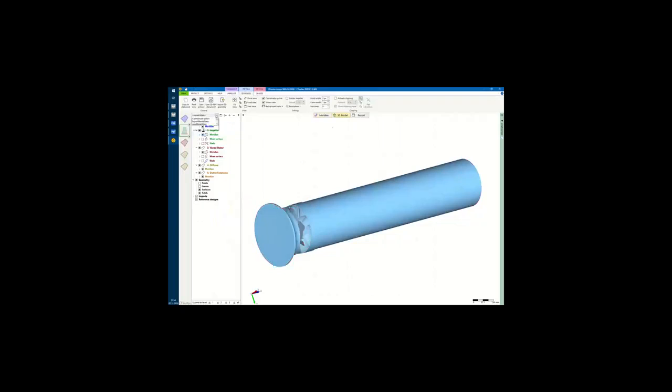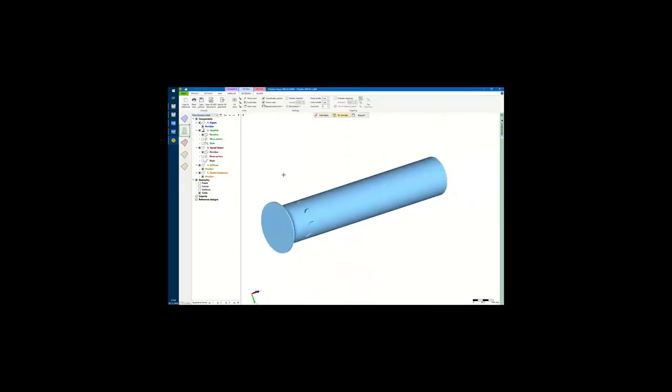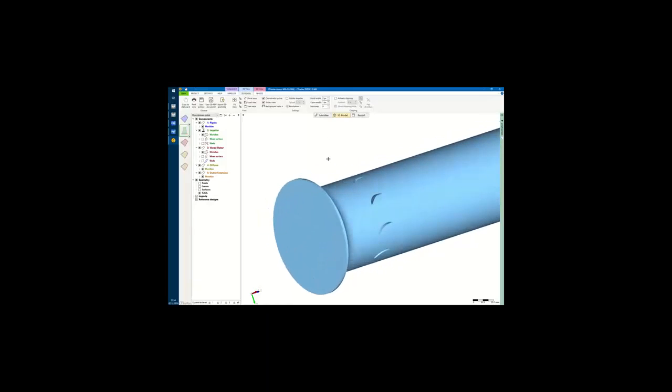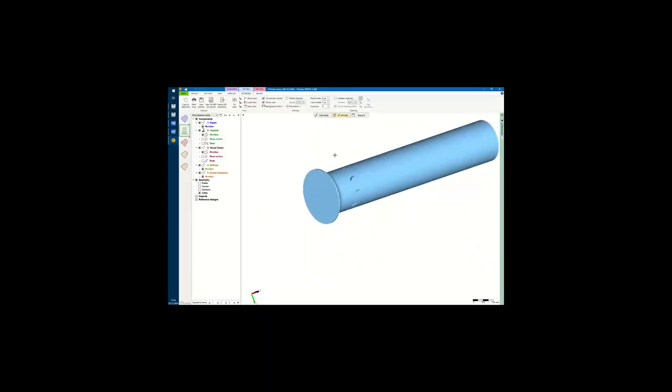All right, so this is the fluid domain that is going to be meshed, except of course for the blade passages, because we use TurboGrid, and TurboGrid does not operate with fluid domains, it's more some sort of curve-based format.